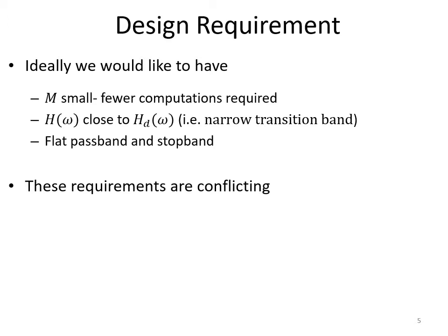So what are the design requirements? That is the fundamental question while designing FIR filters. The design requirements generally fall into three basic requirements, right. So ideally the filter would be the best one as far as the computations required are concerned. For implementation on a digital computer, M should be as small as possible, because when M is small you need smaller memory, you need a smaller onboard computer that can perform these computations in real time, right.